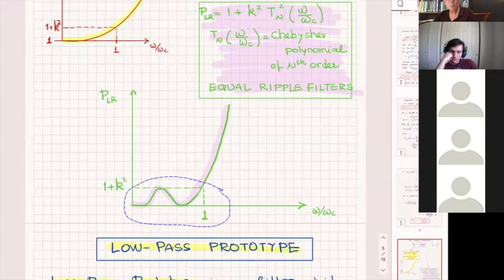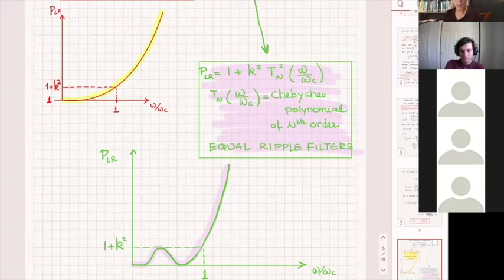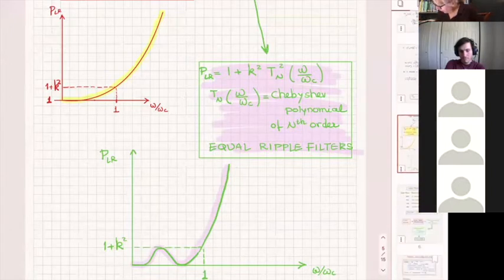Why is this ripple important? As we said last time, the ripple is important because by introducing the ripple, especially in this polynomial, you can improve the rejection. Now, I call it rejection, and you say, what kind of rejection is that, since it goes high? It goes high because we have expressed it like this, the ratio: 1/(1 minus magnitude of gamma squared).